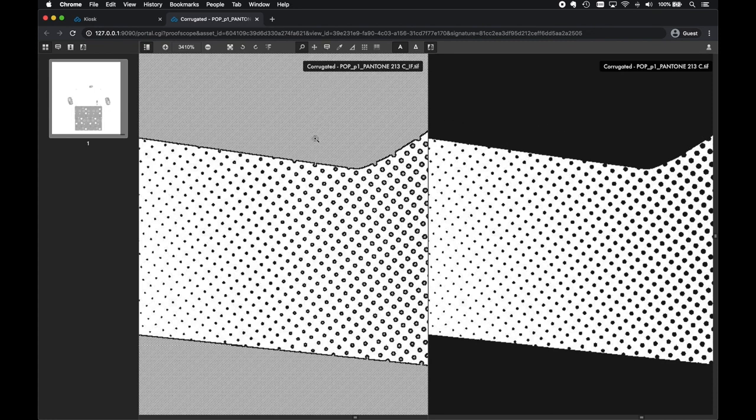With the patterning that's been applied to the solid tones, this allows us to lay down more ink with a better transfer, which gives us better densities or higher densities for solid colours. But with the patterning and the cell wall protection that's applied to the screened areas, this actually allows us to reduce dot gain at the same time, which is something that is difficult to do in tandem. This is also especially effective when working with difficult substrates like fluted board, and it can actually drastically reduce effects such as the washboard effect.